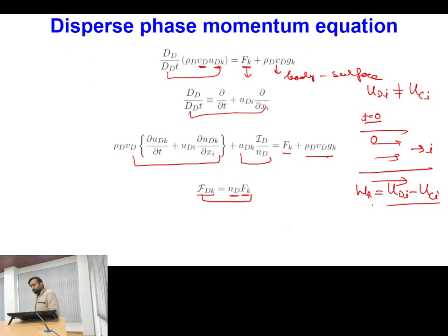What we want to estimate is, in any given situation, of course there will be different dominant forces acting on the particle, but on an average basis, the time taken by the particle to reach its equilibrium is what we call the relaxation time. The formulation of relaxation time will be completely different for different flow situations.